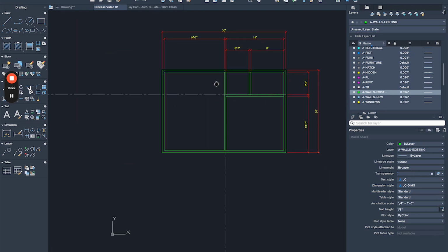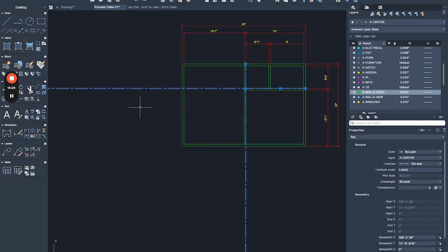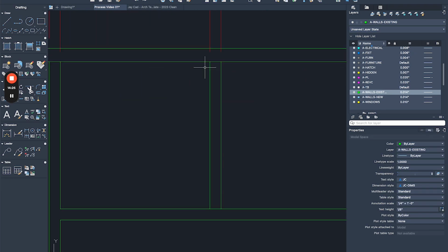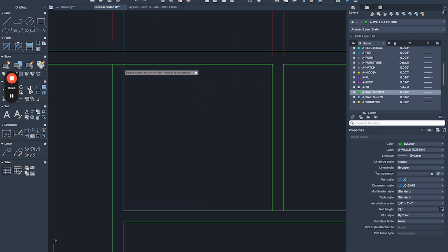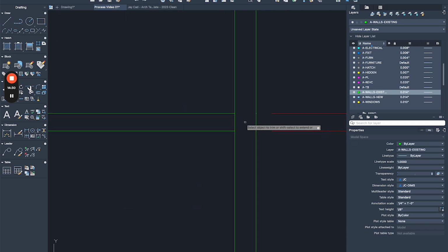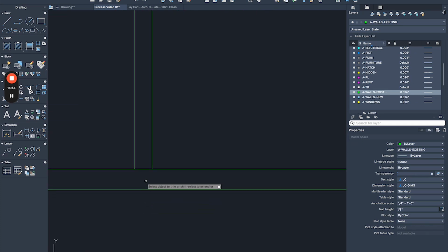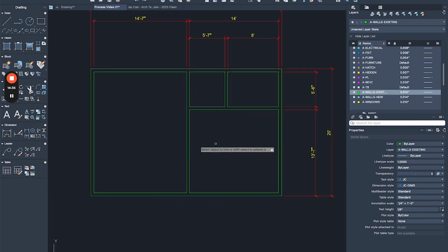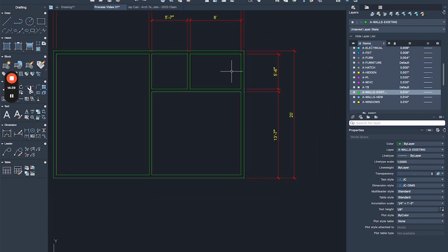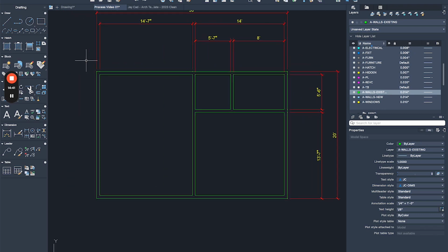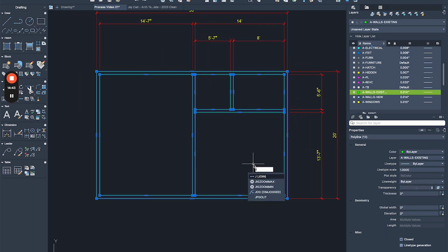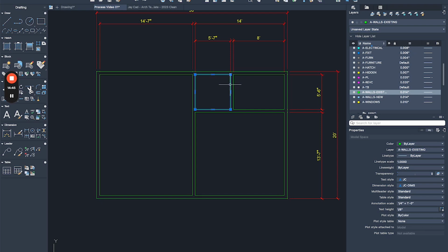All right. So now that I have these, I'm gonna get rid of the rest of the rays. I will do some cleaning. I will get rid of this portion, just so I can have clean wall lines. And you'll see in a bit when we start hatching the walls, why this is going to be handy to clean things and make it easy. And then what I will do, I'll select everything and I will join them. So now this is like a single polyline.